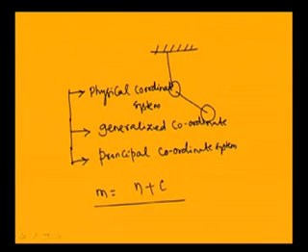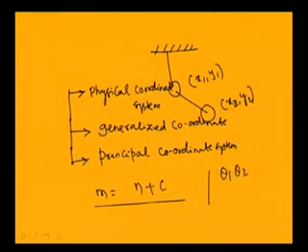In this case of the double pendulum, you may write the equation of motion by using the physical coordinates x1, y1, x2, y2. So, these are the physical coordinates you can use. The generalized coordinates will be either the x displacement of bob 1 or mass 2, so either you can use theta 1, theta 2 as the generalized coordinates, or you may use x1 and x2 as the generalized coordinates in the case of the double pendulum, but you may use x1, y1, x2, y2 as the physical coordinates of the system.